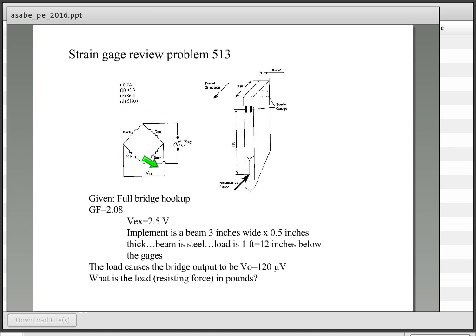So since it's such a small amount that we're usually dealing with, we typically wire them up in what's called a Wheatstone bridge, so that we have compression and tension in opposite legs of the Wheatstone bridge, or we can have dummy resistors if we only have one or two arms of the Wheatstone bridge as active strain gauges.